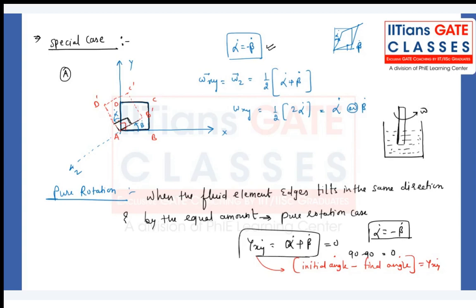When we rotate this fluid, even though it has viscosity, even though this is a viscous flow region, the fluid element in the container will not take a different shape. The shape will be whatever the initial shape was, even after some time. So this is called forced vortex flow. This forced vortex flow is a pure rotation example.